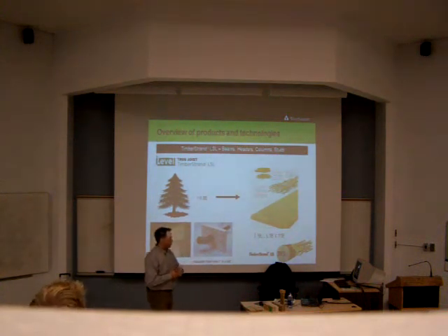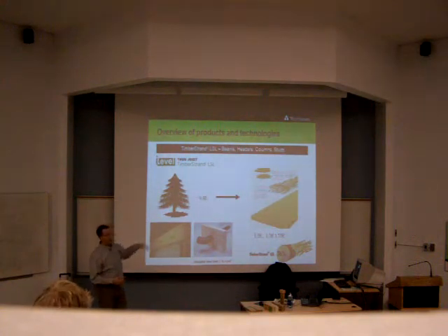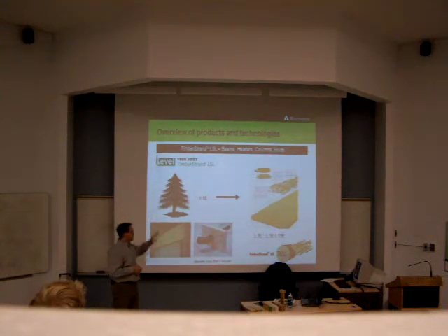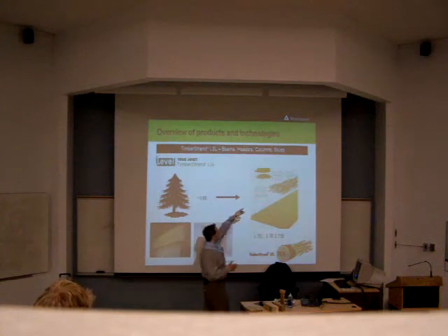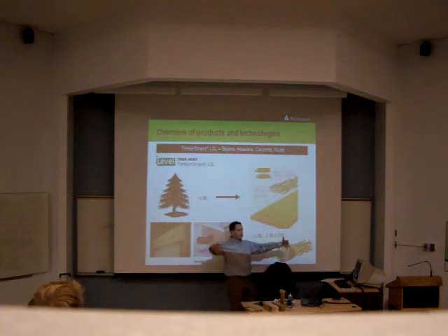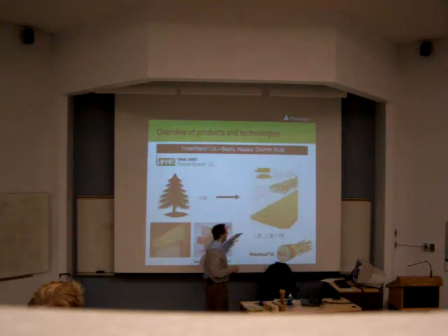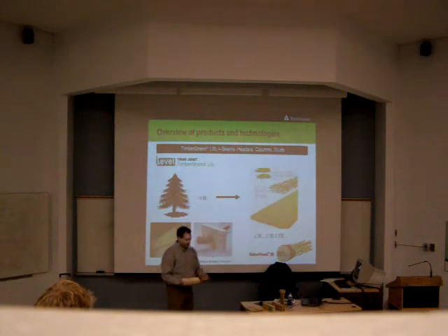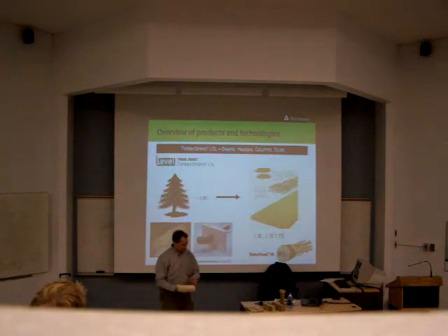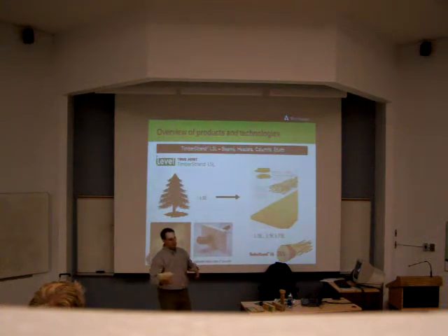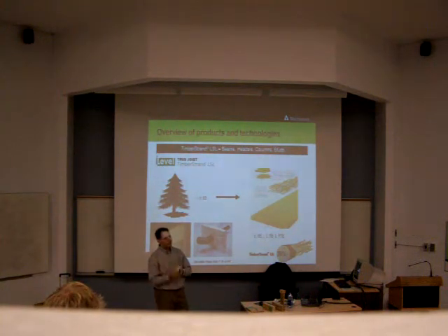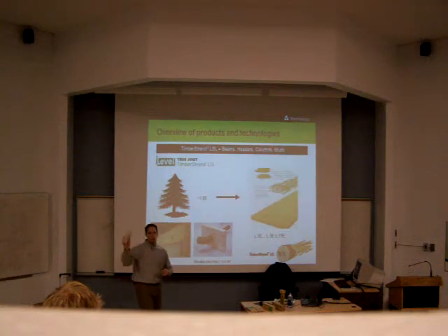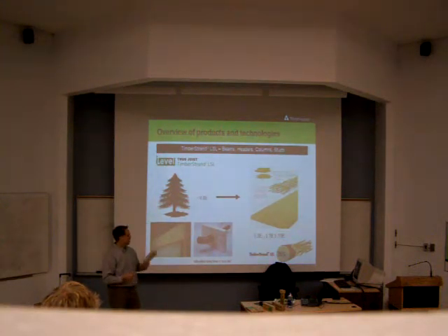So what we've done as an innovation, as a product, is we've taken those underutilized wood species that grow fast, they're in abundance, but they're not used for anything. So we take that weak material and we chop it all up into long strands, because it doesn't matter if we have a nice big billet, we're chopping it all up. And then we orient it all in the same direction. I have a really small piece here, but it looks a little bit like OSB if you really looked at it, but much larger flakes, much longer in size, and we orient them all in the same direction. And then we press it, it's a microwave technology, we have some secret herbs and spices, if you will, out comes LSL. And that's what timber strand is.